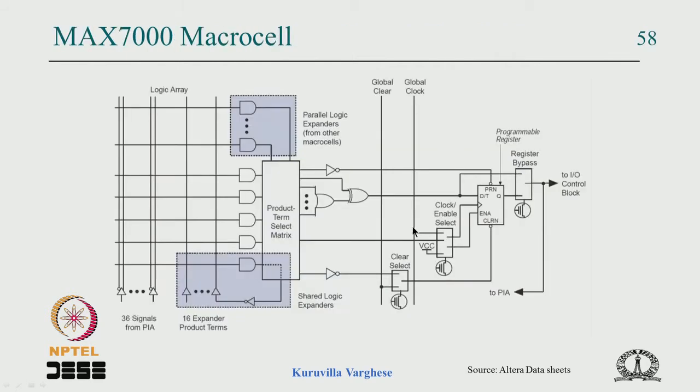So this is the real macro cell, or the logic part of one section. You have one IO pin with a tri-state gate and all that, which is not shown here. So what is shown here is the one section circuit. Basically you have 5 AND gates, and you see one of the AND gates is fed back into the array itself.